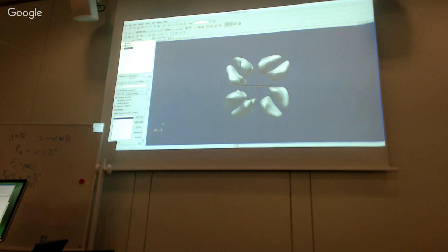So you need one step more. To change the color by the value, you use this coloring option here. By default, it gives me these options: velocity, well, all my scalar things, except VR, which I'm interested in, because I want to display the value of VR here. So to do that, I just tick this compute scalars option, and I apply.